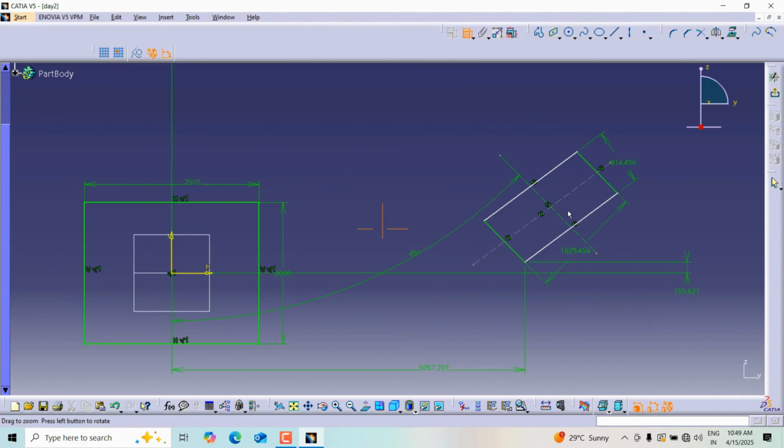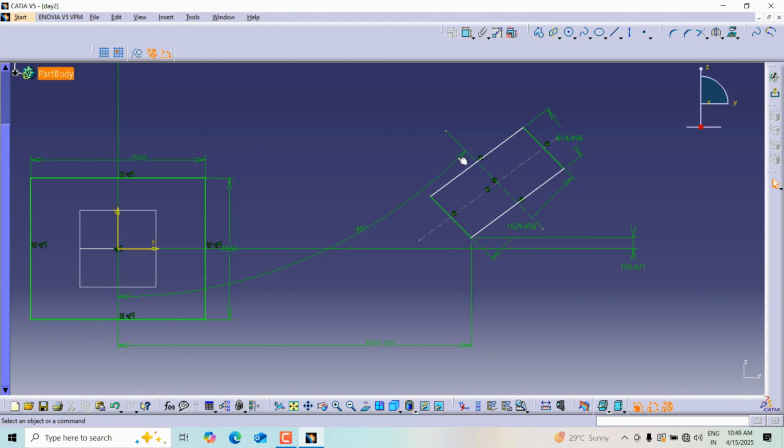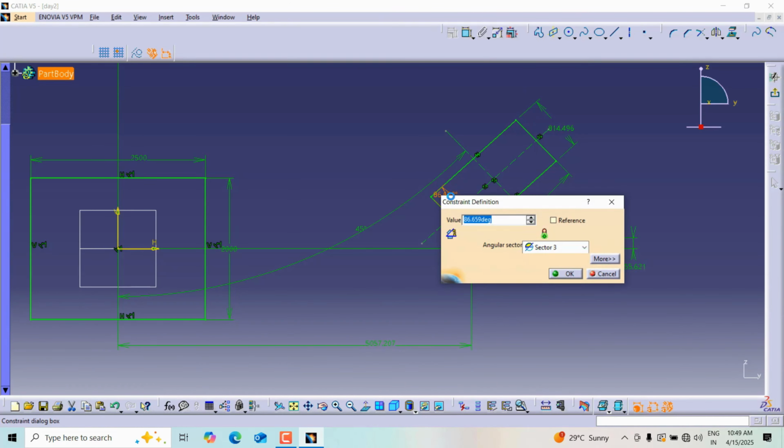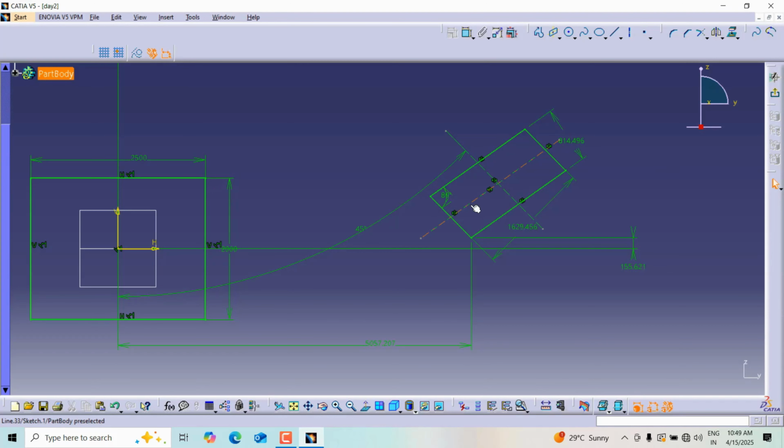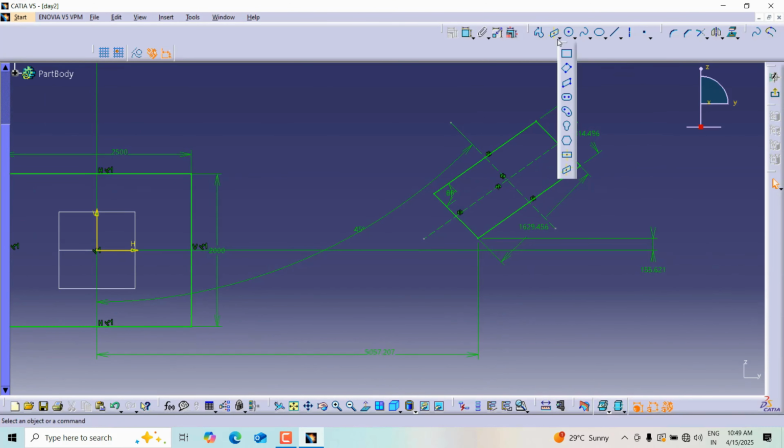Now still this rectangle is not coming constrained. It is because we need to provide the angle between sides also, as it is a kind of parallelogram only. So the adjacent side 90 degrees is not fixed here. You just need to provide the angle and then it will be constrained. I have taken 80 degrees here. So these were the commands related to rectangles here.